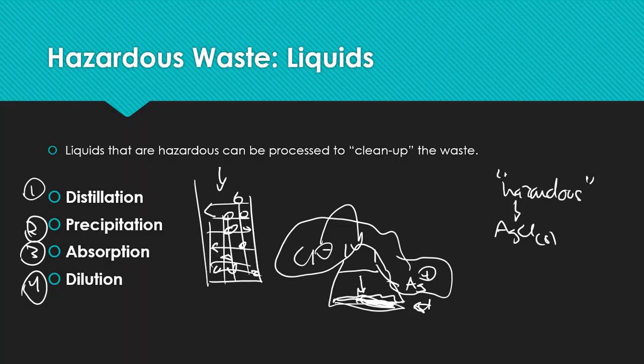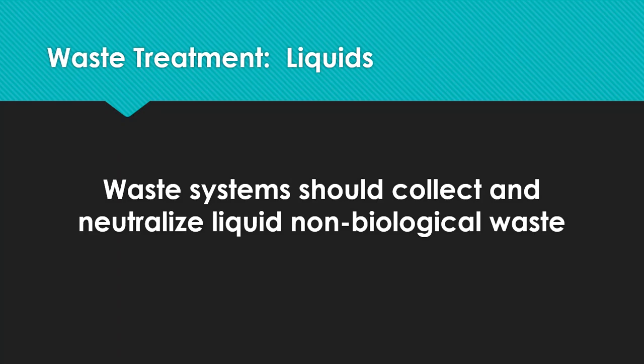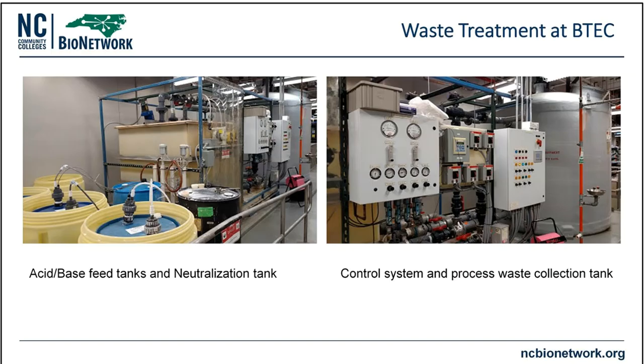So liquids, as you can tell, have many other options that solids do, but they also require more involvement from me than solids traditionally do. As far as liquids go, proper waste systems should collect and neutralize non-biological waste. Here you see a couple of pictures. Over on the left-hand side, these are feed tanks, and those feed tanks are going to feed acid or base into a waste system, so that we can neutralize the threat if that's what we need to do.